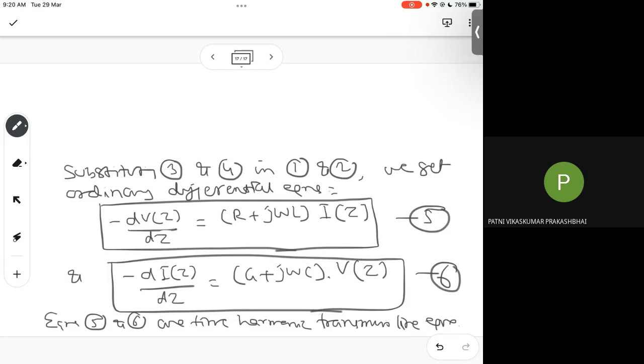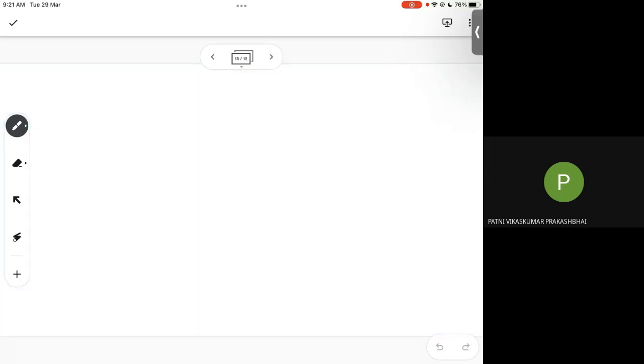At the basic electronics level, or the low frequency electronics level, if you give a 5 volt signal, you will always get that 5 volt output, despite how big your cable is, or whatever current you are expecting, that current you will get. Here, as I said, because this introduces delay and other effects, the transmission line has an equivalent circuit. R, L, G, C are involved. So at every point, my voltage is changing, at every point my current is changing. So what is my aim? When I'm doing the analysis of the transmission line, what actually am I doing? I am interested in how to compute Vz and Iz.